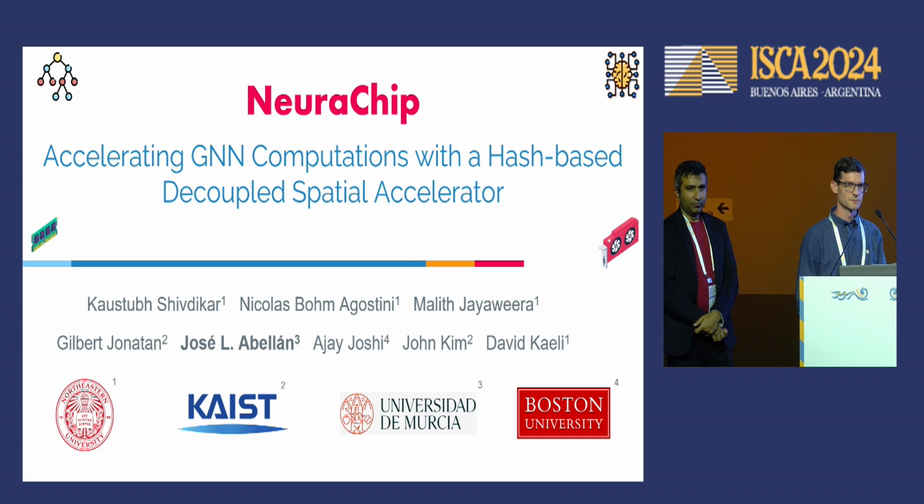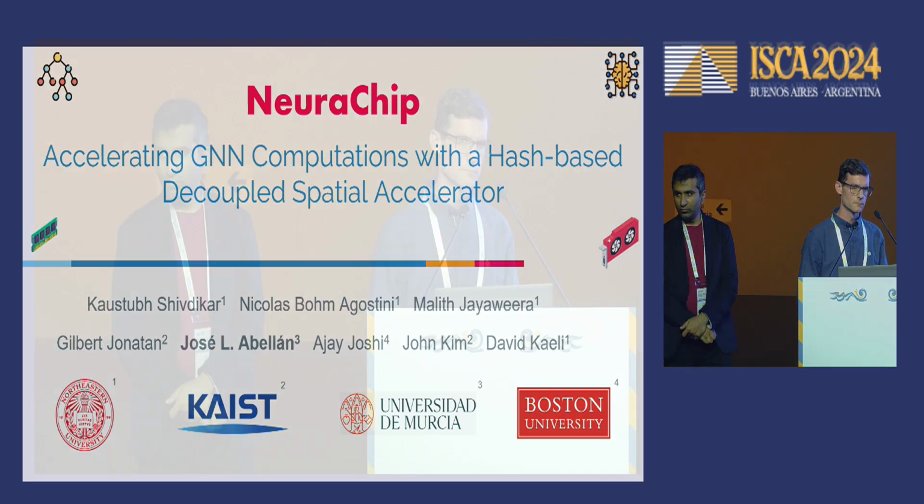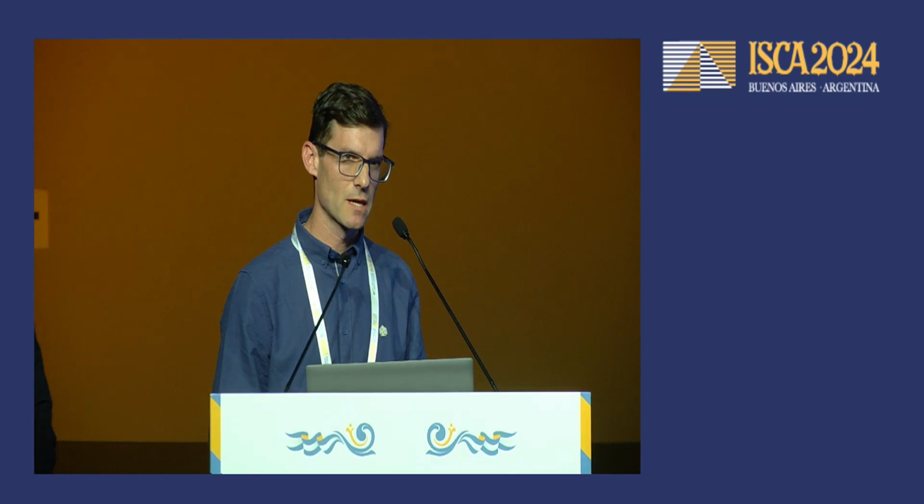Hi, this is Mingyu from Tsinghua University. Very nice talk and very solid work. I'm not sure if I exactly follow the hash part of the work. You mentioned you have higher bits and lower bits hash, and then the lower bit hashing is better. Is this basically the same thing as a set associative cache, where you have the tag, the lower bits of the address as the hashing, and then you have a tag? Is there any difference here?